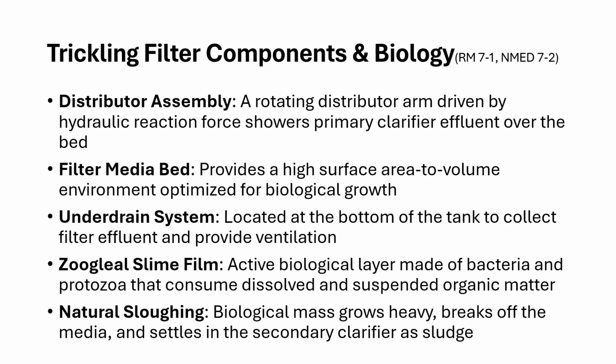And then we've got the zoogloeal slime film, and I call it the slime, or snot layer, if you will. And that's an active biological layer. It's composed of microbes, bacteria, protozoa, and the dissolved and suspended organic matter that's being trickled over that. The microbes, bacteria, and protozoa are going to chomp away or metabolize that as we pour it through.